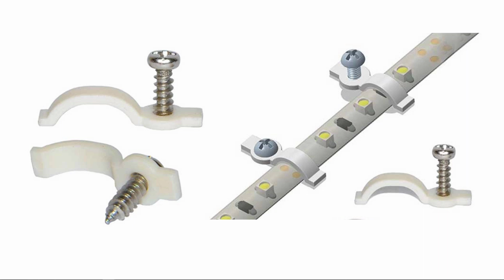Now, if you stick this to bare wood, it's going to stick, but it's not going to stay for any length of time, because as the wood goes through its hygroscopic cycles, that LED strip is going to extricate itself from that surface. Even hot melt glue is not going to stick so good. So I use these little brackets, and if I'm running dual strips, which I do for this layout, I actually get the tab on the other side of the screw to overlap onto the strip next to it, so I can use one bracket to hold down two strips.